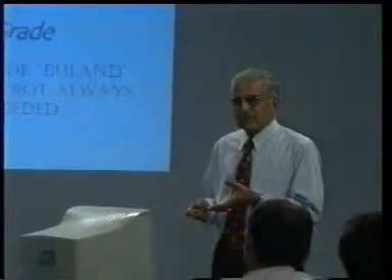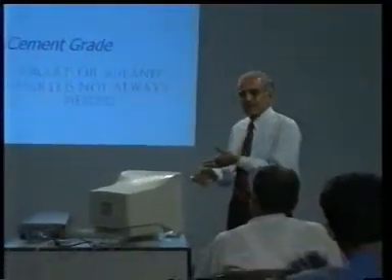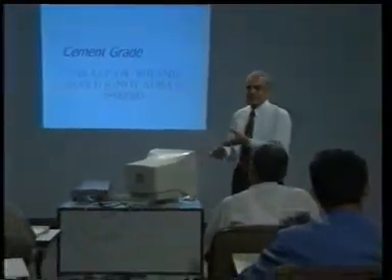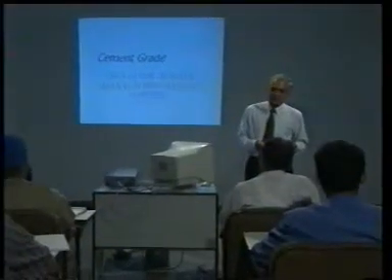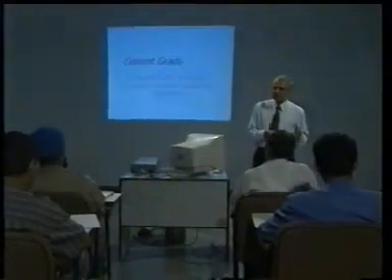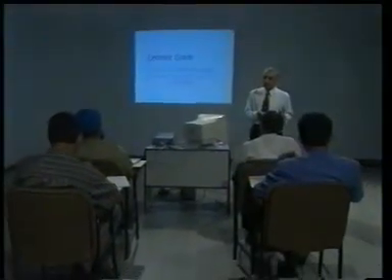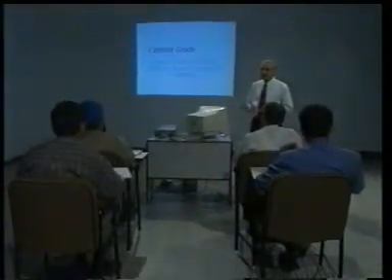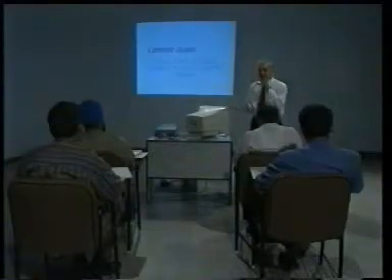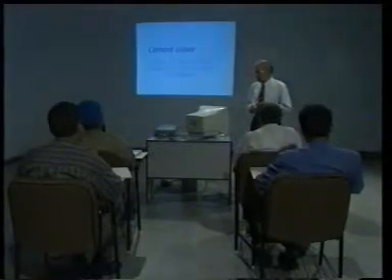The high grade, high strength cements have a high heat of hydration, and the high heat of hydration is going to lead to cracking and other problems on the ground. So, there is no point in using these high grade cements. These high strength cements are meant for special structures where special considerations are taken and very high strengths are required from the concrete. So, avoid using these gimmicks and advise your other lay friends also.